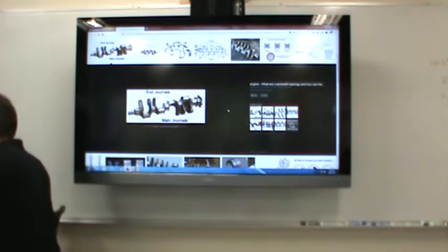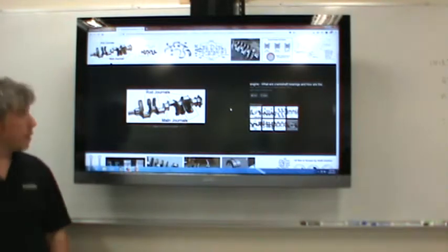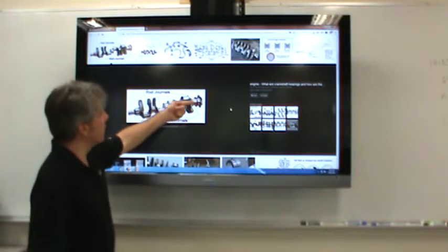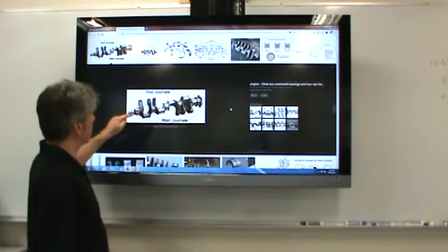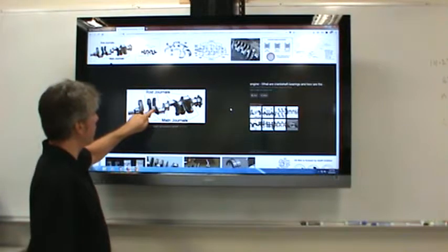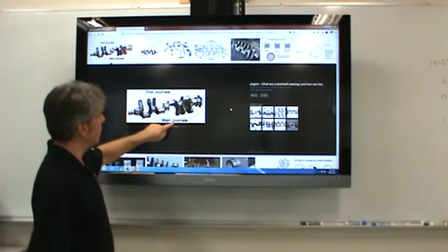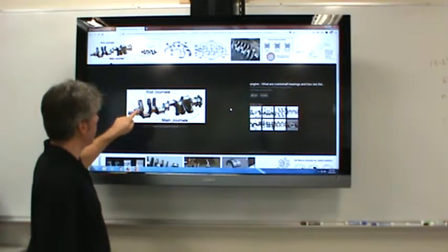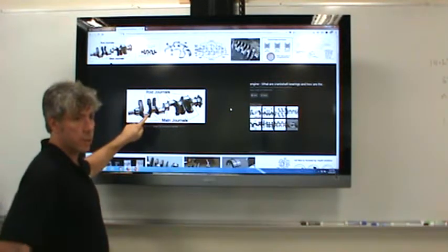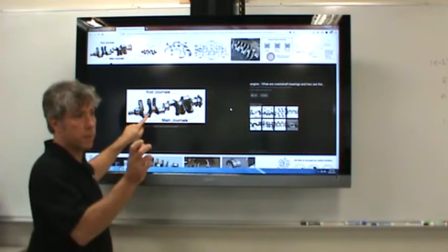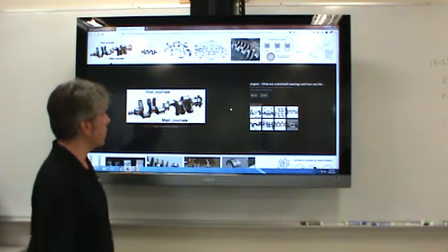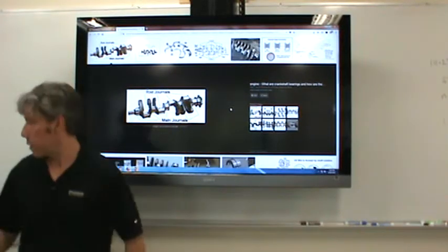Yeah, any of these will do. This is fine. This is what a crankshaft looks like. Anyone know how many pistons will ride on this crankshaft? Can you count them? Look down the main line. That's what's going to be mounted in the block. Okay. So these are main journals, just like the note here says. There's 1, 2, 3, 4, 5. The rod journals. This is where the connecting rod will connect up to the piston. And there are 1, 2, 3, 4. So this is a 4-cylinder crankshaft.